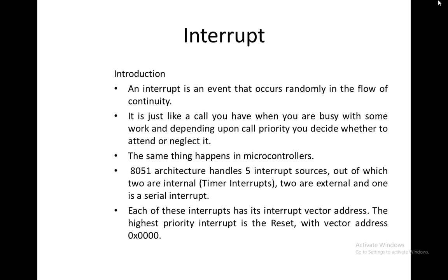An interrupt is created in the 8051, and this interrupt instructs your microcontroller to first cool the boiler by using another method, or to turn off the flame of that boiler. So depending upon the interrupt given, you decide the work. The interrupt decides what work the 8051 has to do. Okay.